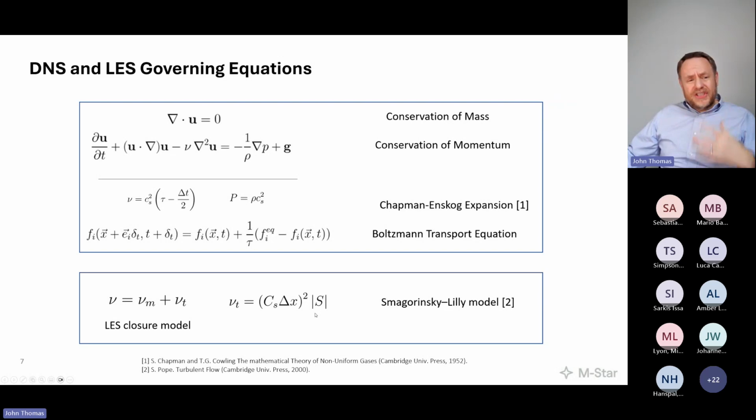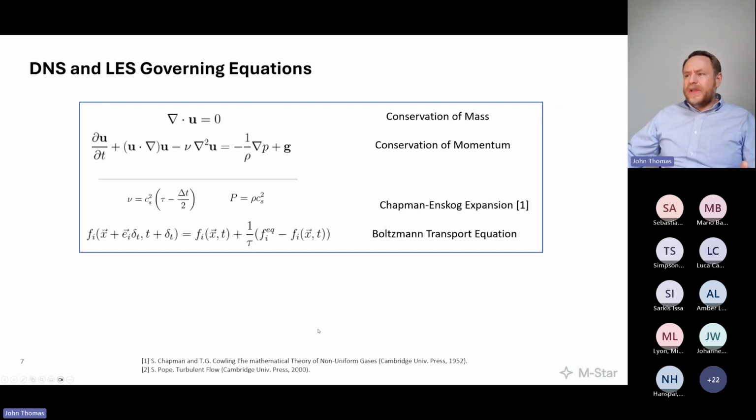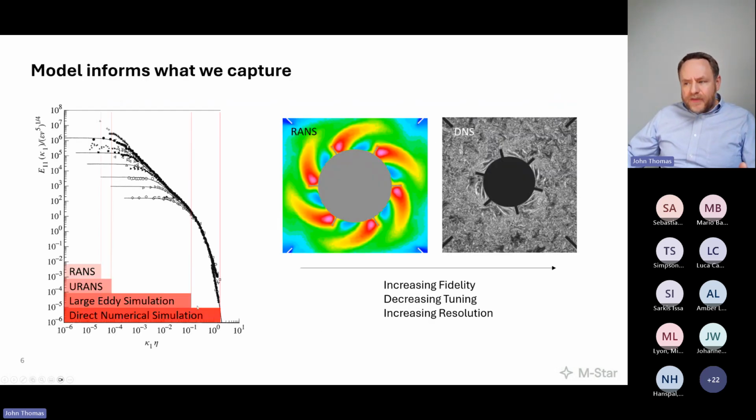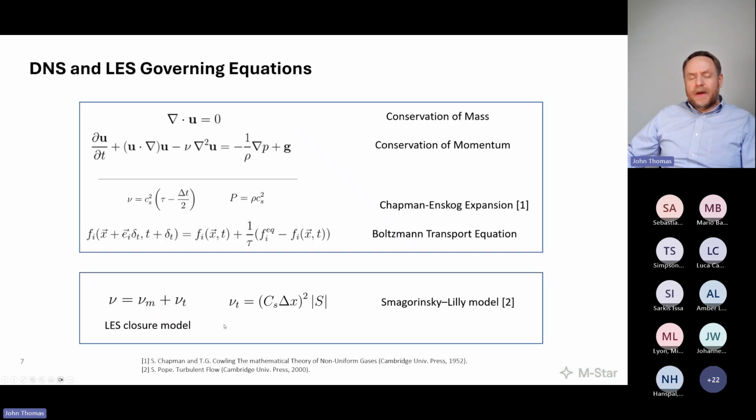But foundationally, this is the crux and claim of LES, that we can bypass some of this subgrid scale and really soften the blow associated with DNS resolution and bend a corner with running DNS simulation, if we're willing to assume that some of these smallest eddies, those close to Kolmogorov scale, can be reasonably represented as having a net effect on the molecular viscosity, which isn't a bad assumption, and it's discussed at length in Pope, but to be sure, you've got to make sure you have a set of eddies that satisfy that close to Kolmogorov length scale condition.